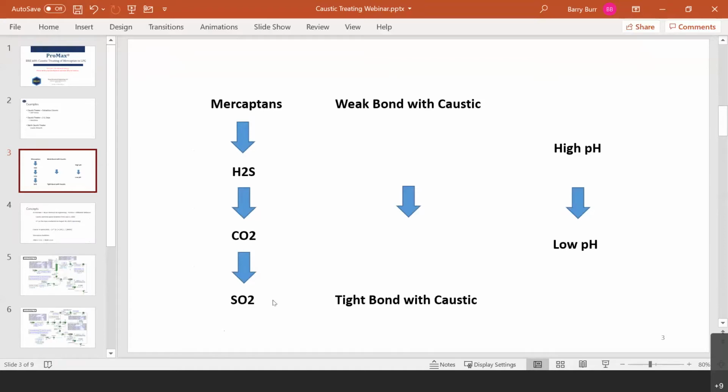So if you have, for instance, an SO2 and CO2 mixture, and you contact that mixture with caustic, eventually any CO2 that enters will just slip through because SO2 is occupying all of the caustic, and any additional SO2 will be picked up so long as there are still available sodiums. So just keep in mind this hierarchy of common refinery acids, or even some other chemical plant acids that you might treat with caustic, and which acid is strongest and will expel or supplant any weaker acids from the caustic.